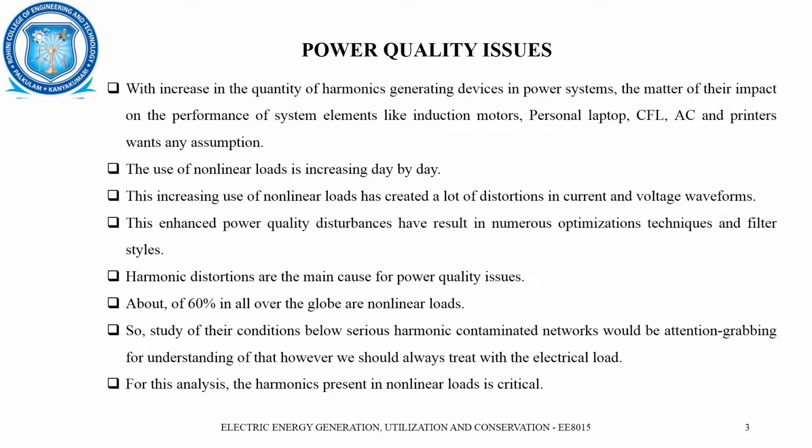So what can we do about these power quality issues? Can they be accepted or not? Definitely they cannot be accepted, because they will damage the load. Sensitive loads will be highly damaged when such issues prevail. If a short time interruption is present, the electricity supply will be absent for a short period. For example, if it is a motor, it will stop, and after some time it will turn on, then off, and again on. In this way, the motor operation and its efficiency will be completely degraded.